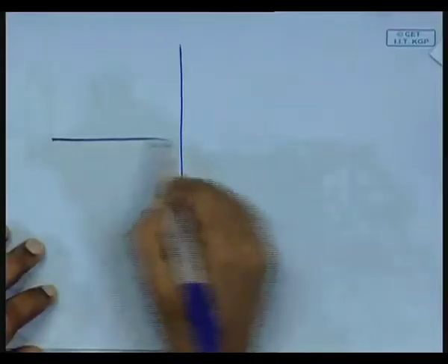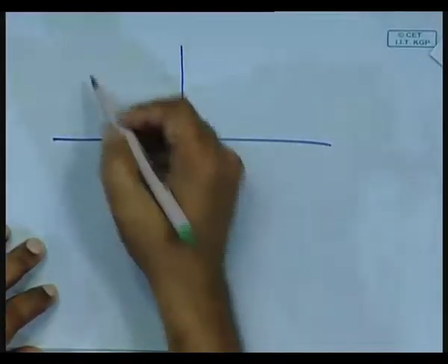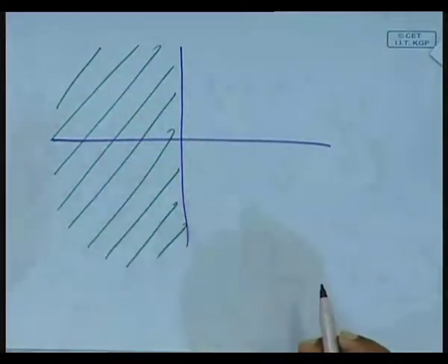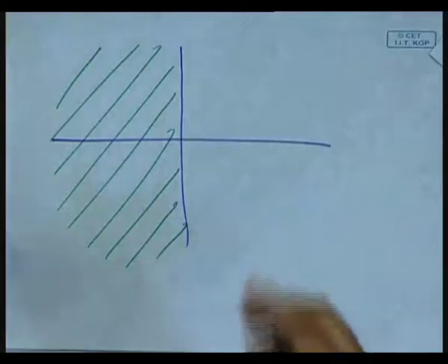So, in general, if this is the Argand plane, this side, the negative side, represents the stable eigenvalues. But this has also given us the idea that if a system is unstable, do not try to control it in a blind way, rather give more attention to the unstable direction, try to push it back in that direction. It is possible. So, what about the imaginary axis?